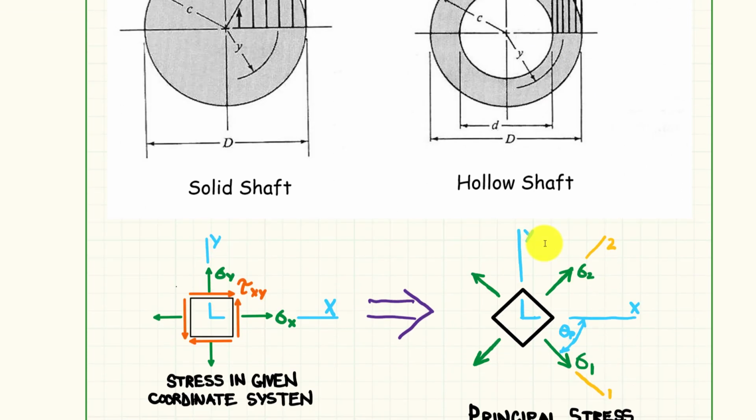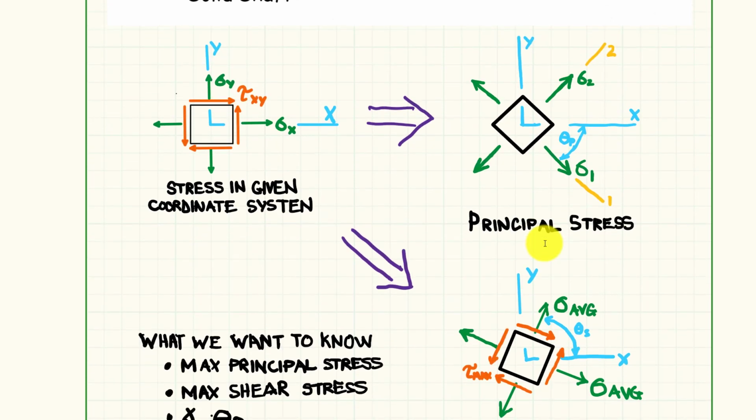and we're going to be able to make calculations for maximum stress there. Now then, let's think about this. We're putting strain gauges on this shaft, and we're going to be able to draw a stress element for this. We're going to convert the strain values we get on our strain gauge unit from those strain gauges over to stress. And once we get the stress values, we're going to go do a Mohr's circle.